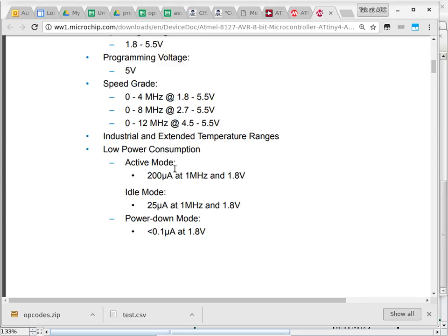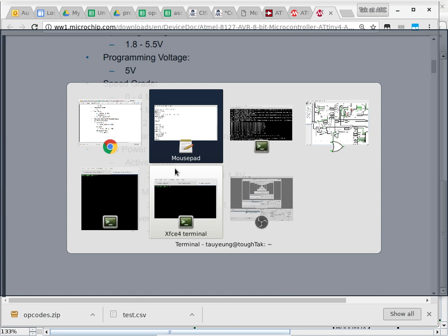And that's because everything can go into power down mode, and then you can wake up four times per second, which is enough to catch that the window has been opened. You can wake up like 4 times per second, and then each time it wakes up, let's say it takes 100 milliseconds to execute. So that will still give you a lot of time to be in power down mode, and that's why you can extend the battery life like crazy, because we are looking at a ratio.